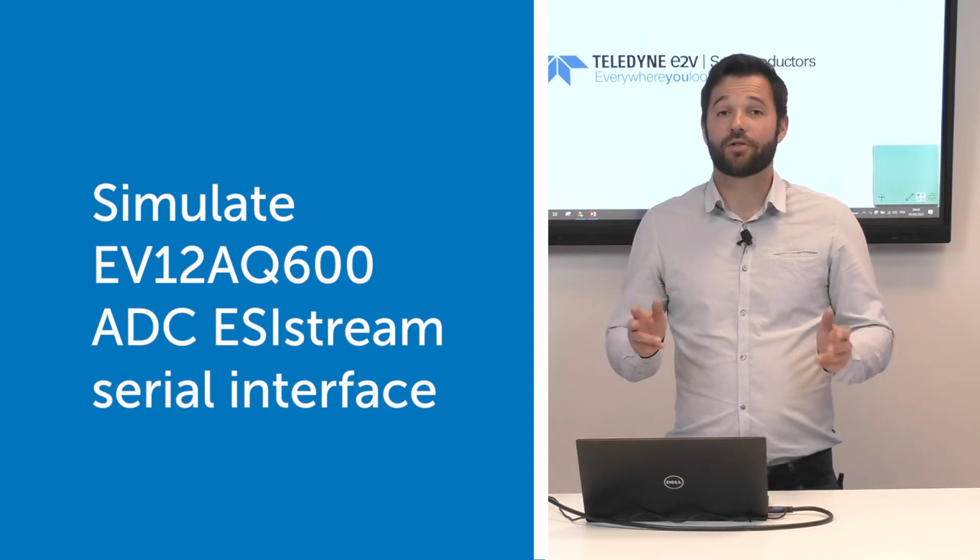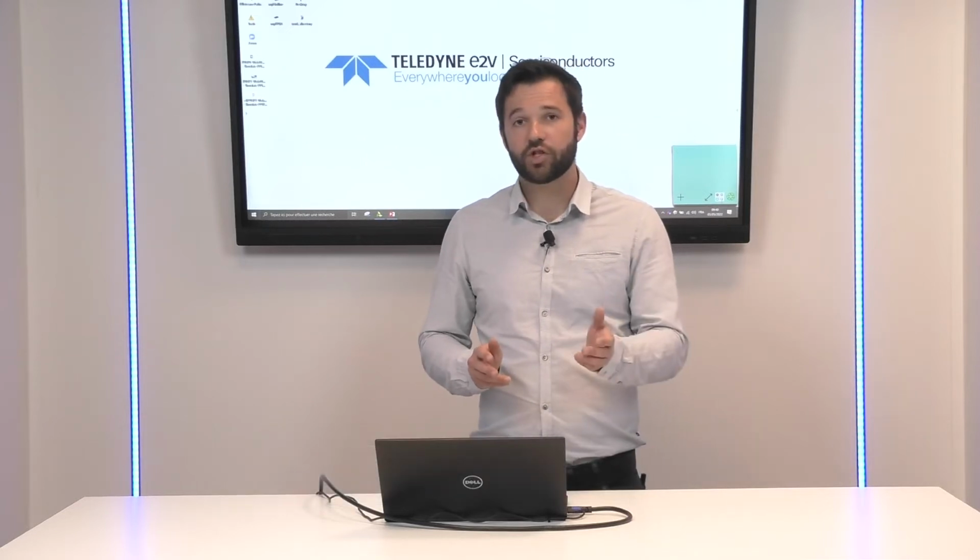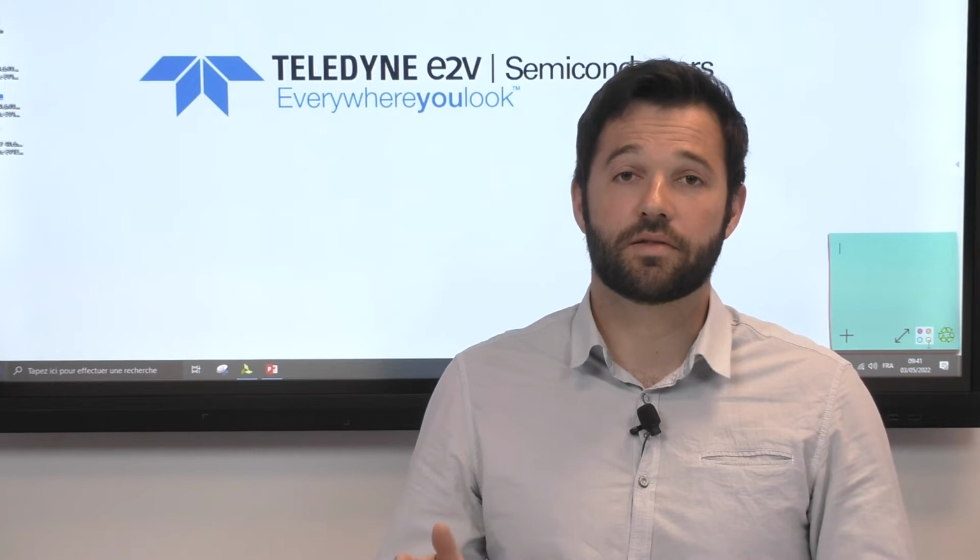Does your application require controlling the sample propagation time between the EV12AQ600 ADC and an FPGA, or synchronizing the ESIstream serial link as quickly as possible? In this video, I will demonstrate in simulation how the AQ600 ADC and the ESIstream serial link protocol will help you guarantee both a short synchronization time and a short total link latency. Then, we will look at how to ensure a deterministic link latency.